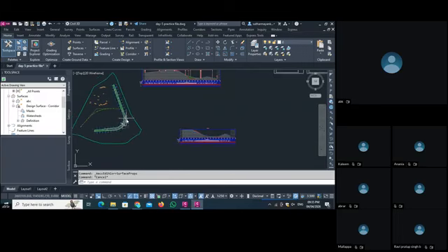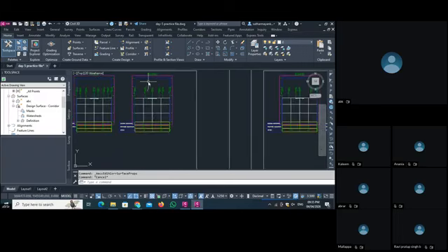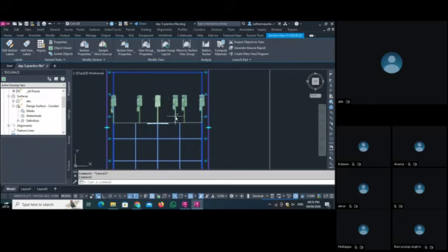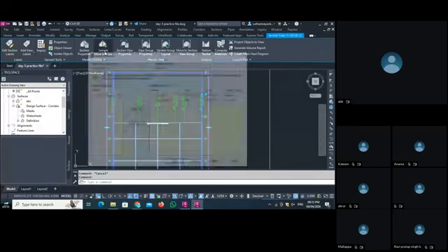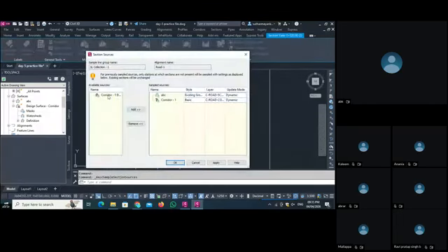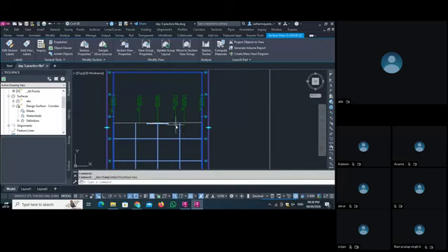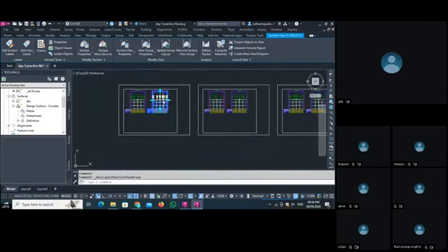Now what I do, I add this surface to our section view. I select the section view and click on more sources. See, now our surface is here, which is not added in our sample cross section view. I select this and add it here. As I add it, I click apply and OK. After doing this, I have to update the group layout. Once I do this, all the groups are automatically updated. It will take some time, but all your groups are updated.